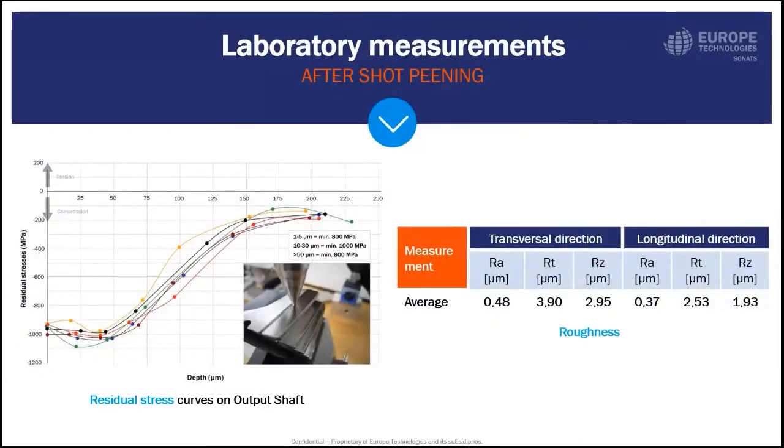So the last characterization is to demonstrate the consistency of the process. Usually we pick up a small batch of parts and shot peen 5 parts according to the same recipe and perform XRD diffraction. What we observe is that the residual stress distributions on the 5 profiles are roughly the same, as the uncertainty of the measurement by X-ray diffraction on steel is roughly plus or minus 30 megapascal. And it results in an Ra value of 0.4 micron.